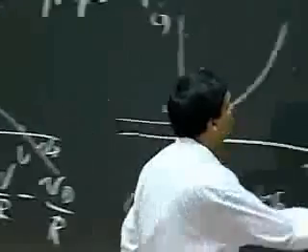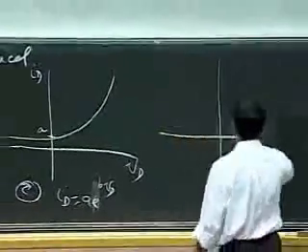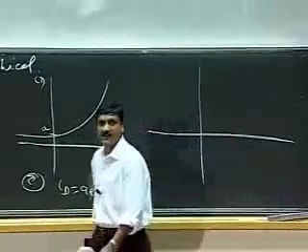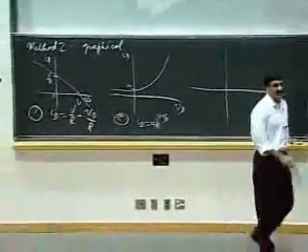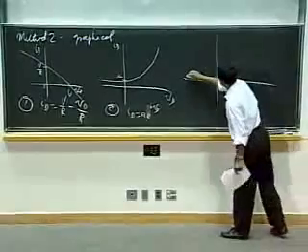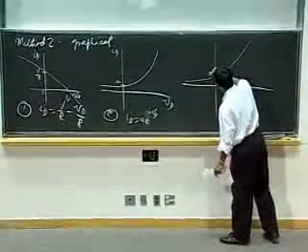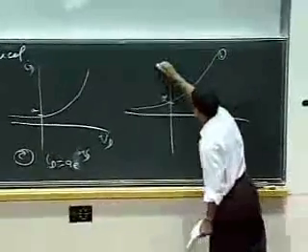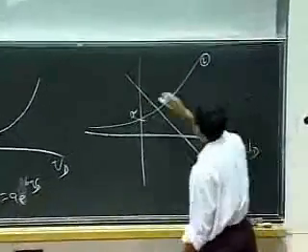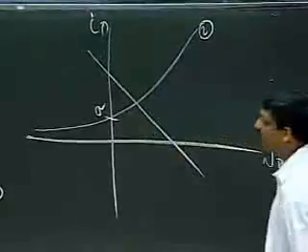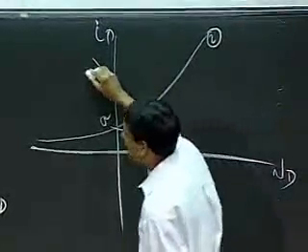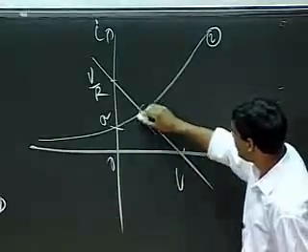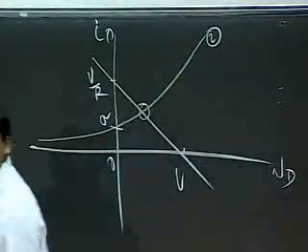So what I can do is simply solve these by superimposing the two curves on the same VD ID template and finding the intersection of the curves. So I can take this curve corresponding to 2, and this curve corresponding to 1, and this is V divided by R, and this is V, 0, and I can find the intersection point.